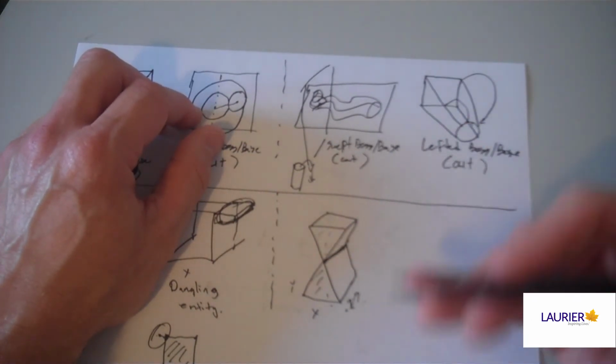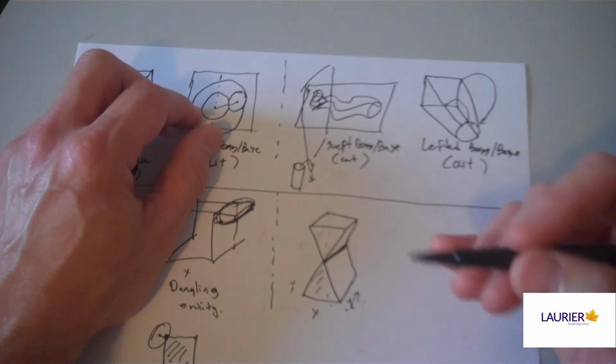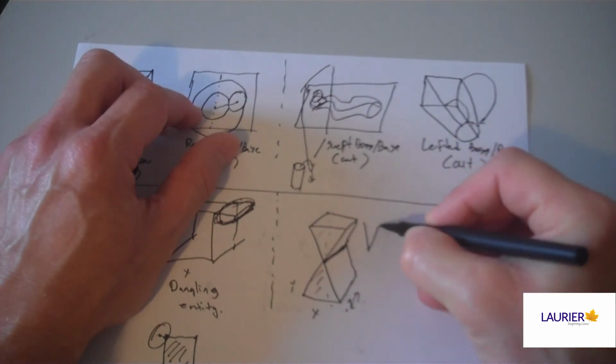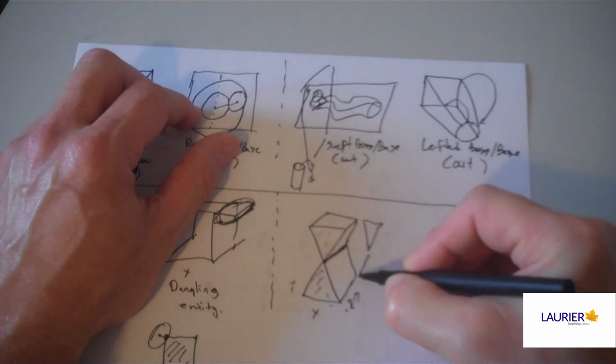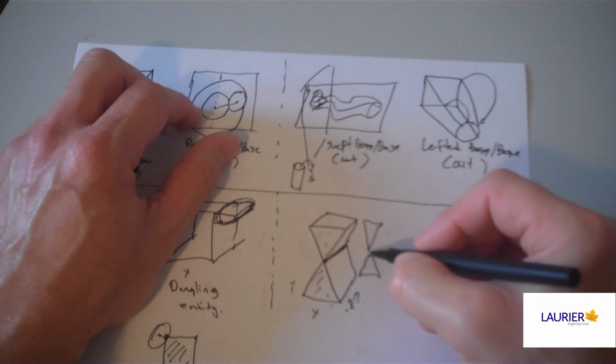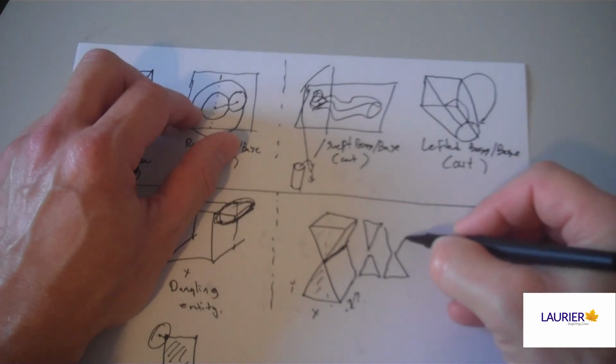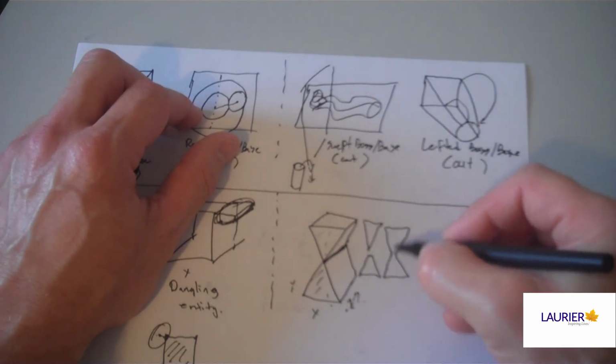The answer is that we don't know, and neither does SolidWorks. Mathematically, if it belongs to one solid, then the other is missing a vertex, which is not good. If it's two separate pieces, no matter how small this gap is, we're good to go. If it's like this, and there's a little opening so that this line is continuous, it's a continuous contour, and that's also okay.